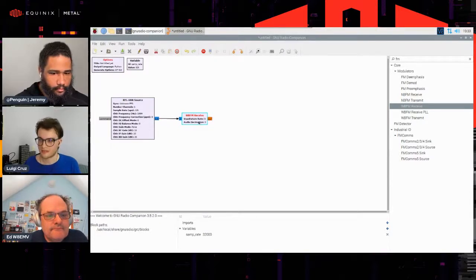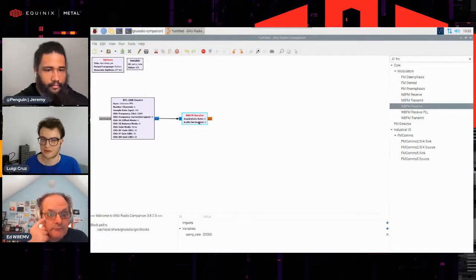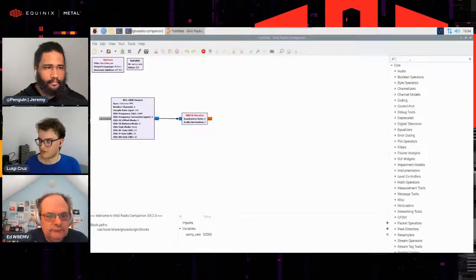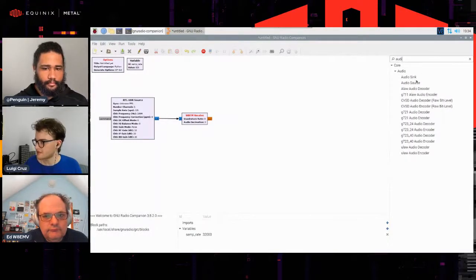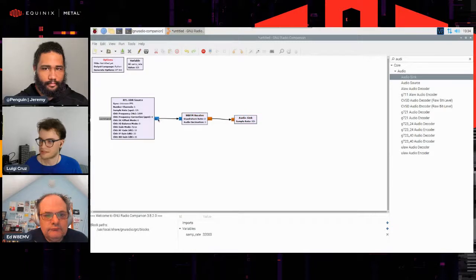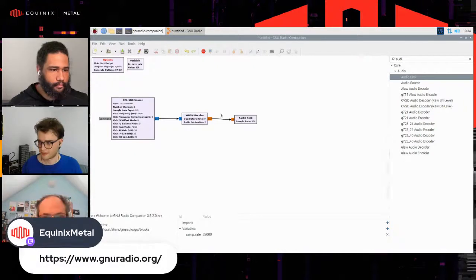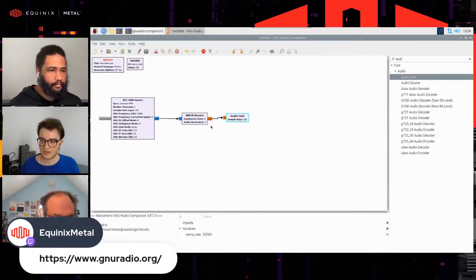And you need to make, I won't explain everything here because it can get quite complicated with sample rates. You need to decimate the signal to match the modulation rate. But the idea is that there are blocks, and the blocks are interlinked with the outputs and the sinks and inputs. After you have a demodulated signal, you can output to your audio interface using the audio sink right here. And you can notice that the color of the link changed. So the radio will output a complex signal, and this one will make it a float signal. This is the voltage levels of the signal. You don't need at this time the IQ signal, the complex signal.